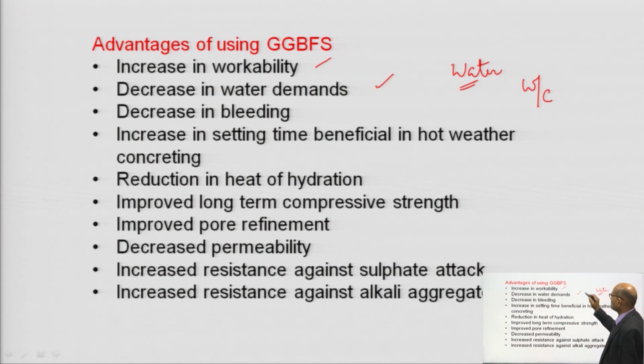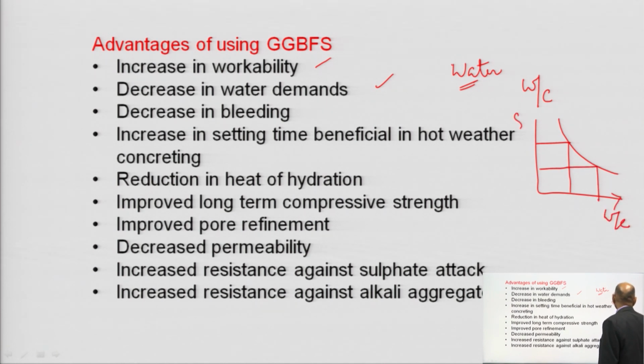Once water demand is reducing, what will happen? You will get improved strength, because of the water cement ratio requirement. This is your strength and this is your water cement ratio, if you see this curvature. Okay. So, you get better strength.